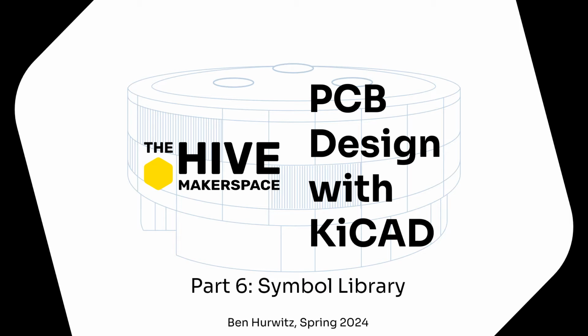One thing I mentioned during that process, and that was featured on the original EDA design flow in part 2, was library management and the idea of using only project scope libraries. But when we actually did the design, I ignored this for simplicity and time constraints. In this video, I will walk you through library selection and generation of a single project scoped symbol library to package with the rest of your project and keep your work insulated from external changes.